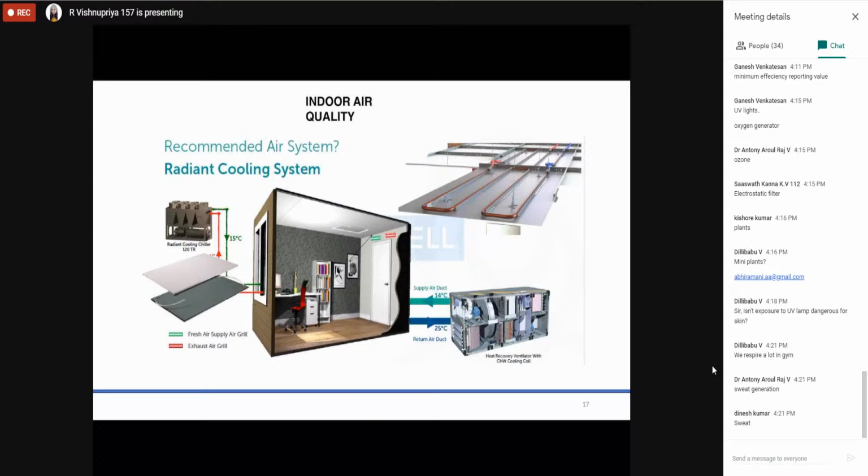Just imagine the capacity remains the same, but earlier I was giving 50 TR with 8,000 or 10,000 CFM. Now, for the same capacity, I'm giving 20 TR in the periphery without adding any fan, and 30 TR of AHU I'm supplying.